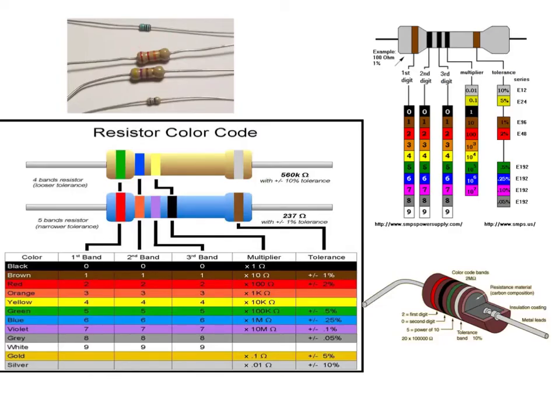Now here is what resistors you will use in the lab look like. They are carbon resistors, and they are color-coded according to this key down here, to tell you what resistance it has. The unit for resistance is the ohm. There's the Greek letter ohm right there. And it has multipliers and bands on there to tell you what it's worth. So for example, this one over here is coming from this first digit, a 1, the next two digits, zeros, so 100. Multiplier is times 1. So this is just a 100 ohm. There's the actual answer. 100 ohm resistor here.